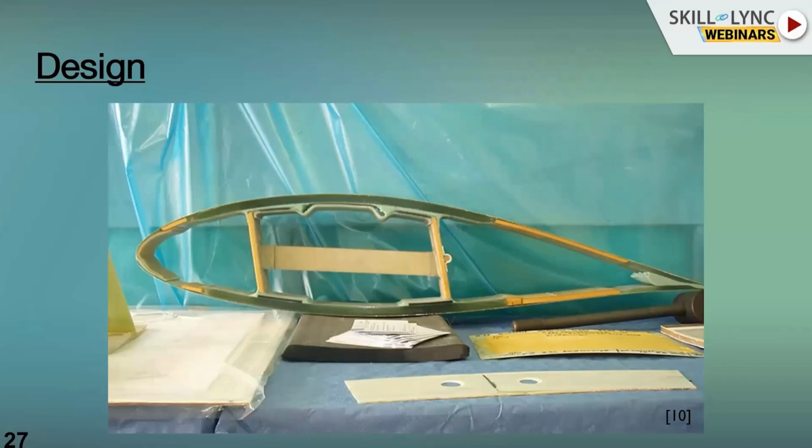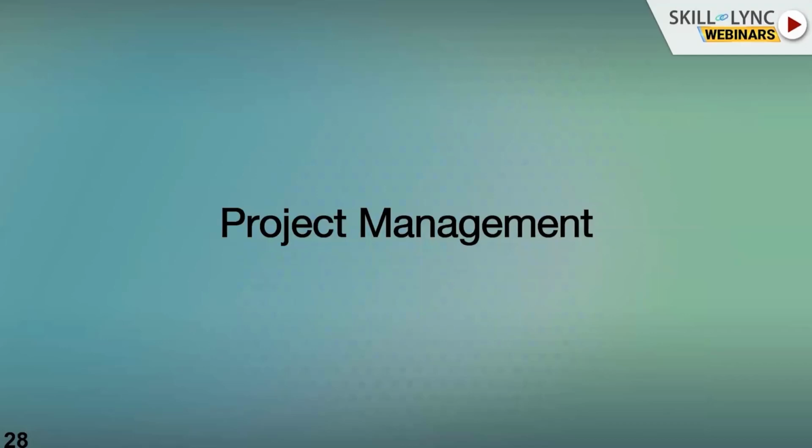In case you go for a 100-meter blade or 120-meter blade, you are required to mold in three to four stages, and internal stiffness is more. And based on the wind condition and turbulence level, the profile also will vary. For all these things, actually, project management is very important.